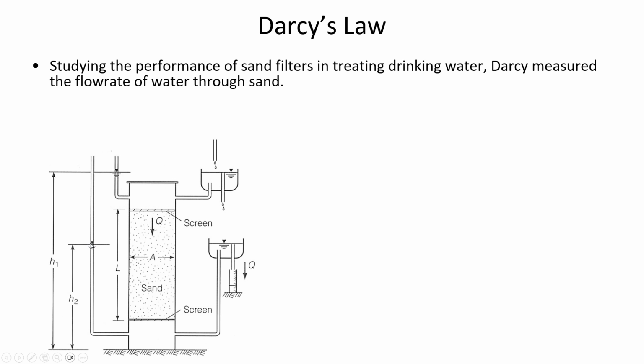This difference in head, if the water wasn't flowing, then the piezometer would rise to the same level. So if there was zero flow rate, if there's sand in here but an impermeable barrier at the bottom, like a clay plug or a piece of plastic, so that the water isn't flowing through it, then this piezometer, which measures the pressure, would rise to the same height.